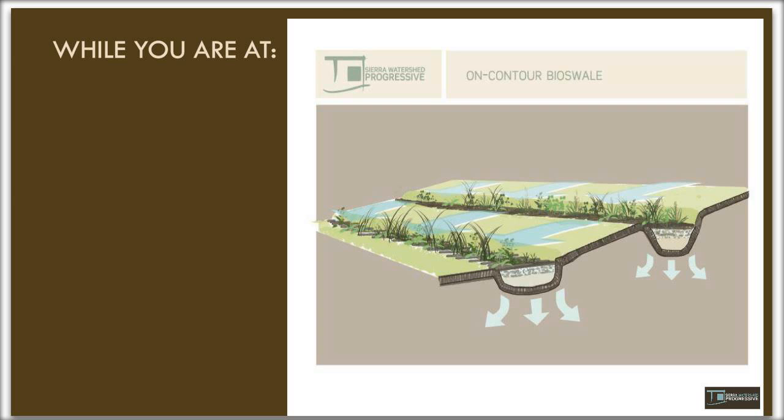But we want to try not to mix stormwater and graywater to the point where it would ever pool and run off. So we want to look at what is coming above our mulch basin. Do we want to use that water or do we want to route it around? There are a lot of instances where we have put mulch basins right next to a rain downspout, and we want to make sure not to direct that downspout right into our mulch basin, or if we do, we had better turn that into a stormwater basin and use our graywater irrigation only in the summer.